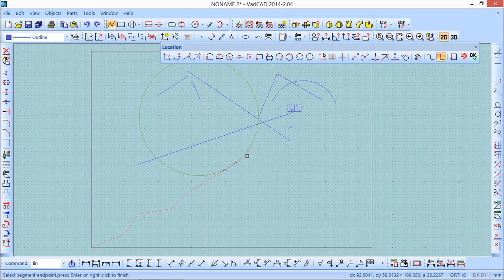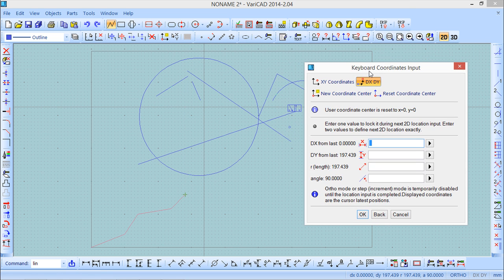The last option of this is something called fixed length arc, angle or coordinate. And basically it opens a dialog box where I can give some information. Okay, I can work with the absolute or incremental. I can define a new coordinate system, whatever I want. Sorry, I will keep the incremental. And from the incremental, from the last point, I say that I want to work with a fixed distance, for example.